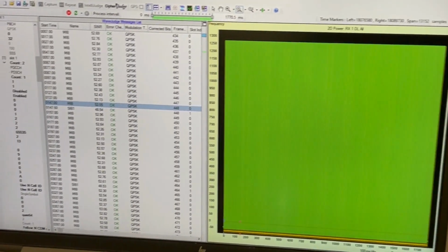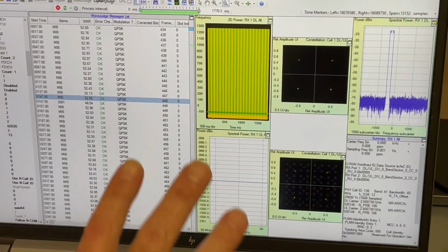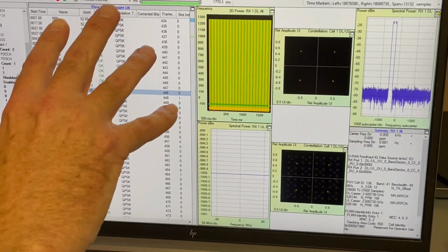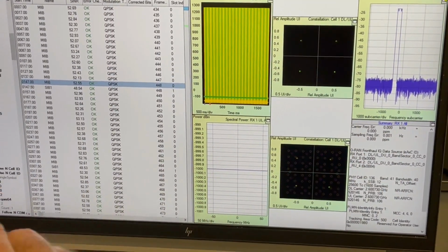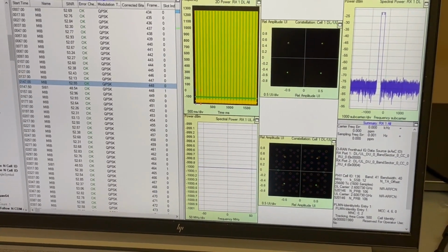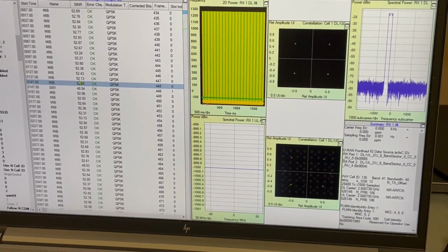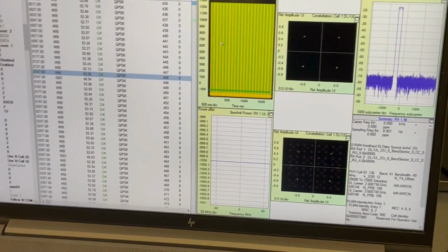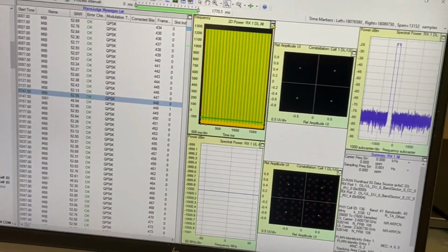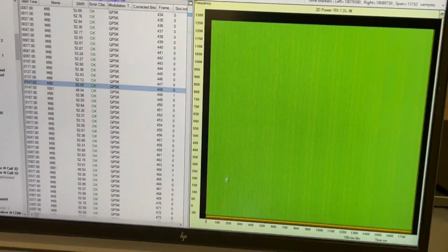So I'll go here, and the WaveJudge software is interesting because, just a side note, it decodes the protocol stack, the messages, but it also decodes the layer 1 physical layer, and it's all correlated. So as you step through and look at different messages, you can see what complex numbers, IQ data, went with each message. Very interesting. Okay, now we'll go look at those SSB blocks.